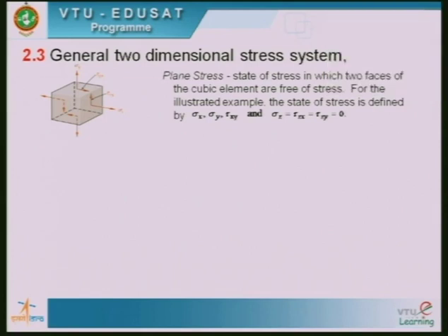Now the general two-dimensional stress system. In case we don't consider the stress acting along an axis, this is called a plane stress state. Plane stress is a state of stress in which two faces of the cubic element are free of stresses.